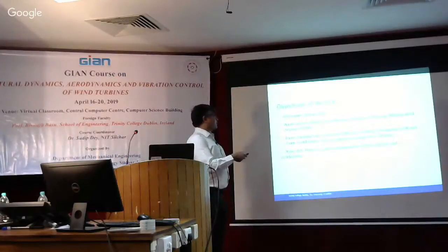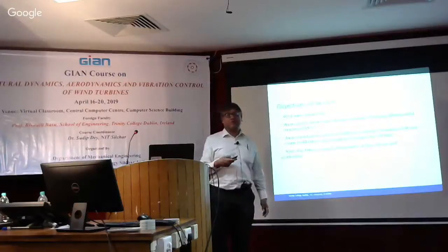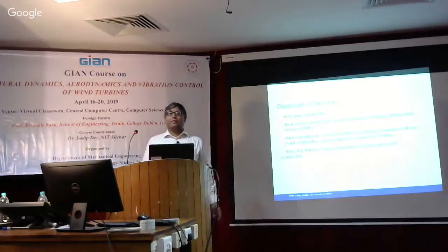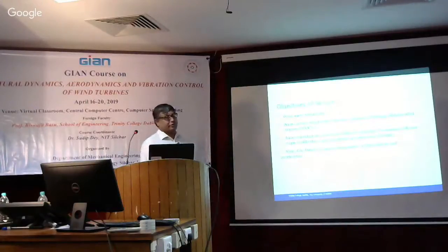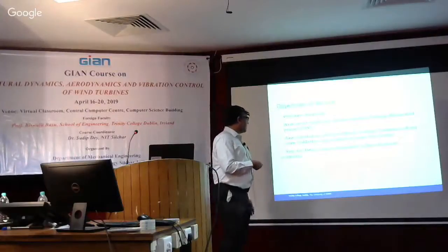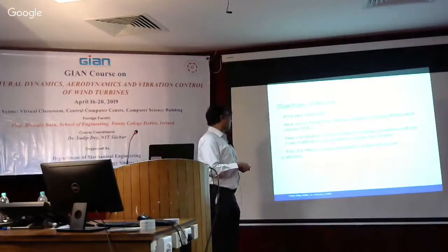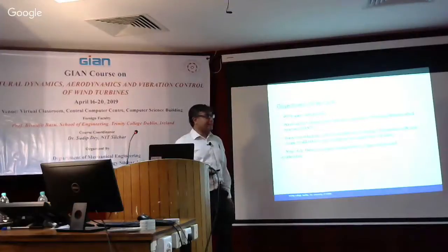Wave-current interaction is another area which has not been looked at, and only recently we have done some work. Even in industry, they don't have all the knowledge available to design all these things, but it's only recently that these areas are being studied. A wave travelling on a current is affected, with a frequency shift and shape modification in the spectrum, as I said. That's very important to consider. And the Airy theory for computation of flow velocity and acceleration is not valid because it is based on potential flow.